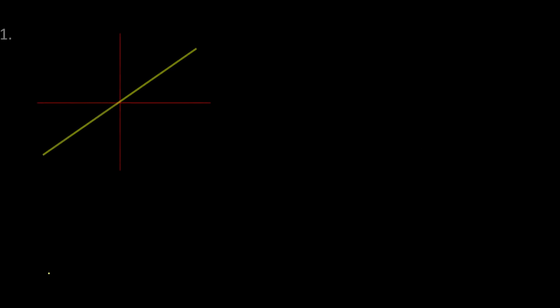Let's start from the first problem. The y-axis denotes the value of the current and the x-axis depicts the value of the voltage. This particular IV characteristic follows y = mx. So it is basically a line which is passing through the origin. It means that this element is a linear element.